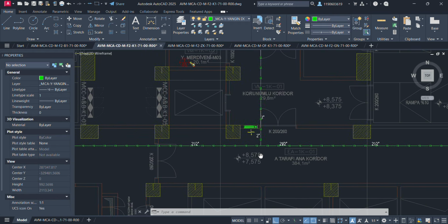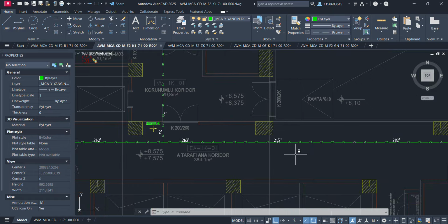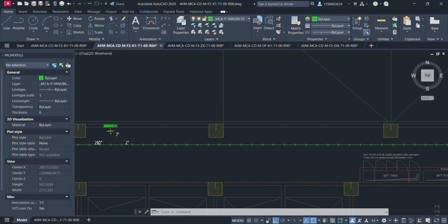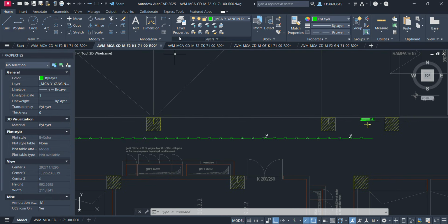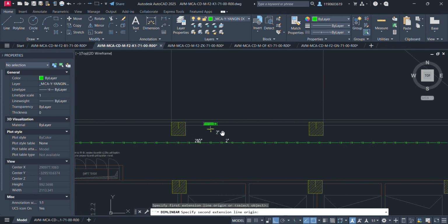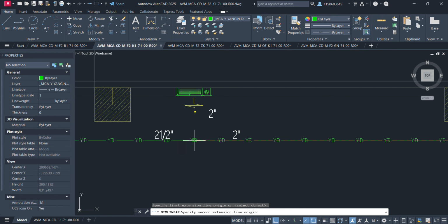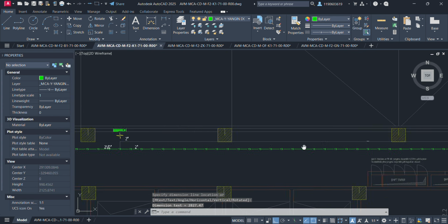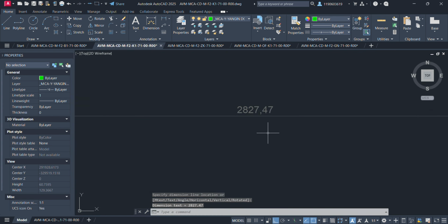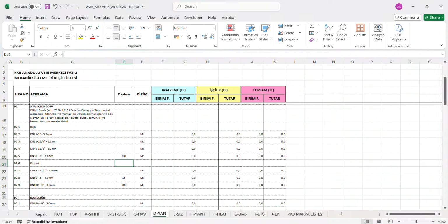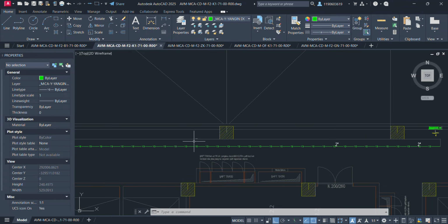How sprinklers are used. Sprinklers are strategically distributed on surfaces or walls within each room or space, ensuring even coverage across the area. Engineering calculations are essential to determine the optimal number and distribution of sprinklers based on the room size and type of activity: office, commercial, industrial, etc. Temperature control is key to the operation of the system, with sprinklers activating when the temperature rises above a set threshold.